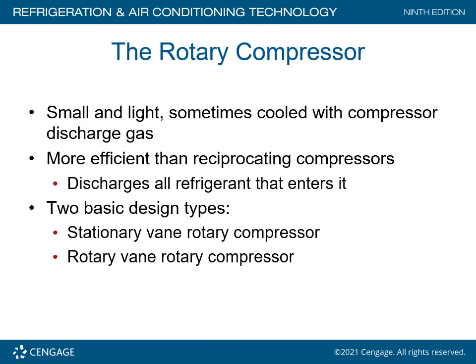Rotary compressor: small, light, and sometimes cooled with compressor discharge gas. It's more efficient than a reciprocating compressor. It discharges all refrigerant that enters it. There are two basic types: the stationary vane rotary compressor and the rotary vane rotary compressor.